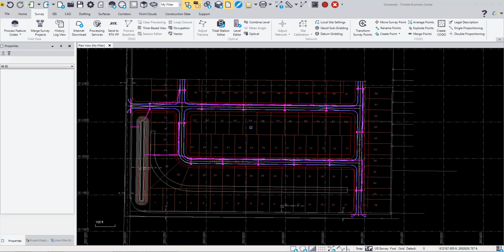With the Survey Intermediate Edition, you can perform an office site calibration. So you need a couple sets of points. Here I have some line work, and I'm going to bring in a CSV file of my control points. So I have a file here I'm going to drag and drop in.